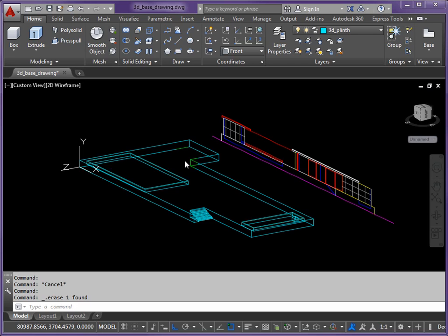We're at the next stage of the Barcelona Pavilion model. We'll start to deal with the walls and everything else in the model. So we do need to do a bit of layer swapping around here. The layers that are currently visible, I want to lock those so I don't accidentally move things out of position. So I'll start off by locking these two layers.